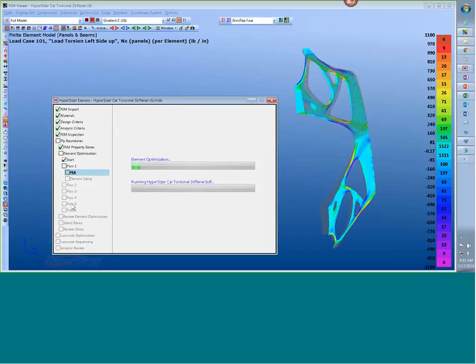The software is automatically updating the FEM with new optimum results, submitting the FEA solver, waiting for the solver to complete, reading in the stress resultants from the solver, doing another optimization, reading the displacements from the solver, and determining what part of this structure is most efficiently stiffened to reduce deflection. Is it 0? Is it 45? What ply orientation is the best to use for this solution?